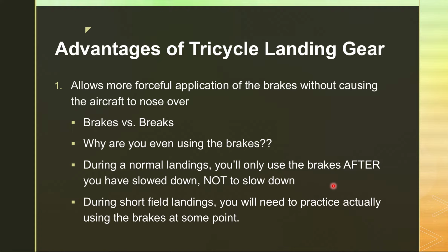It's more than easily doable. The POH says you can land that aircraft at 600 feet of ground roll. So we have more than a 50% safety margin over what it says we need. And I'm going to say 9 out of 10 times the pilot lands and just stomps on the brake like it's in a car. Okay, your airplanes generally don't have anti-skid braking systems in them.